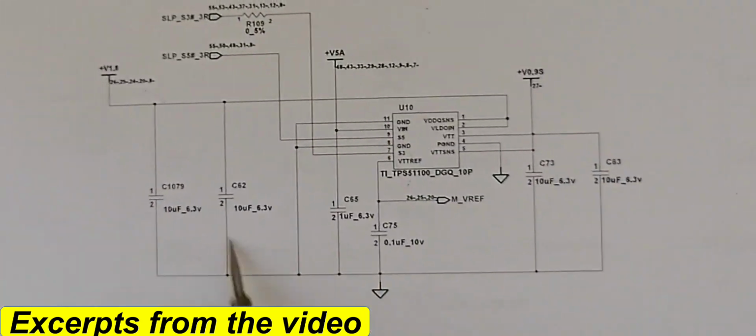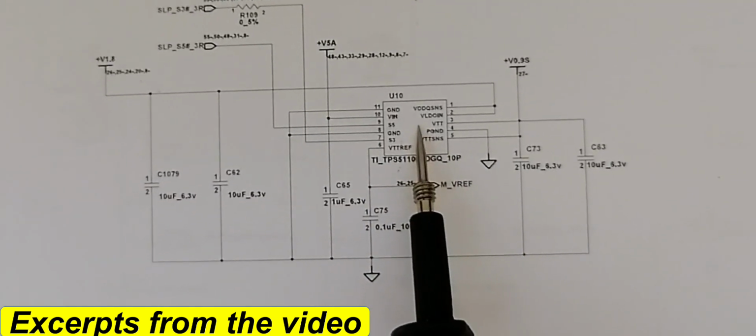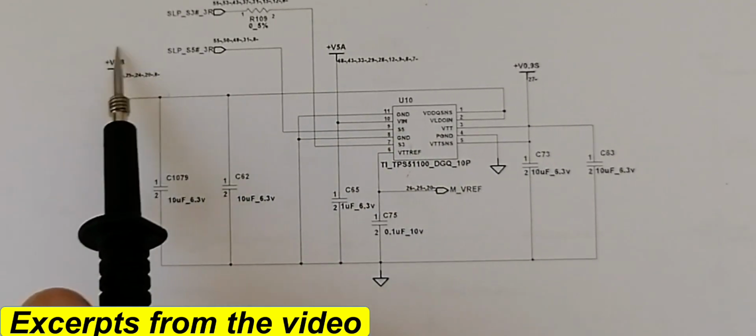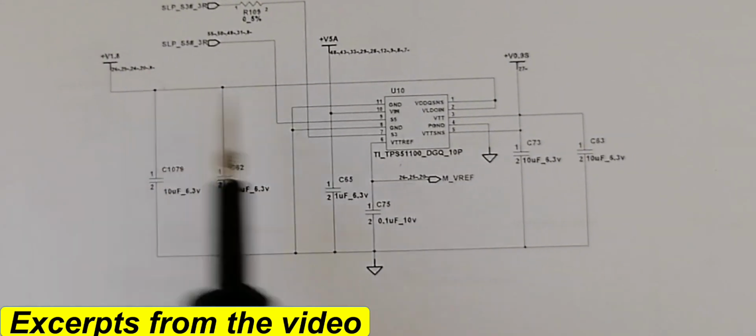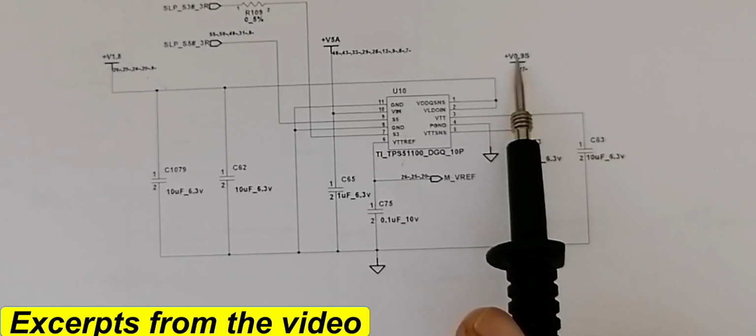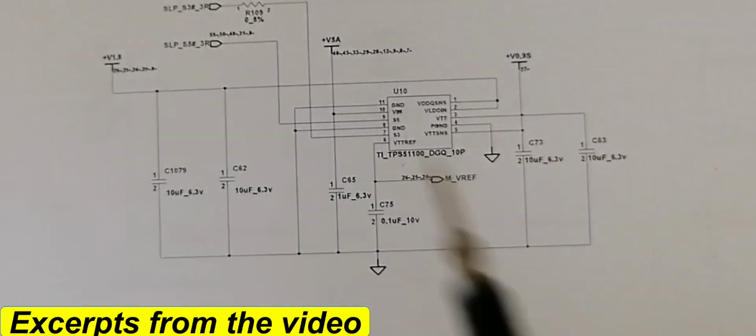So for example here, this is the schematic. This is the IC that powers the VTT for the RAM. Here we have the main voltage, as you can see, 1.8 volts, and over here we have 0.9 volts. So the voltage for the RAM and the voltage for terminations.